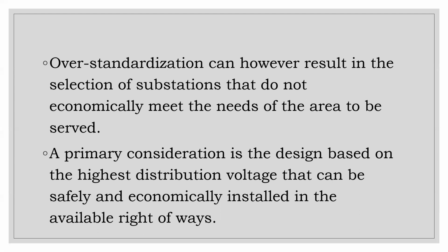So if the standard thing is that you have double breaker, double bus, right? It doesn't mean that when you build a substation to serve that new community that is being built in the hills of Clarendon, that you're going to use double breaker, double bus. You may be able to do a single breaker, single bus down there, and the people will be happy. They don't mind losing power once a year, right? You don't need to.